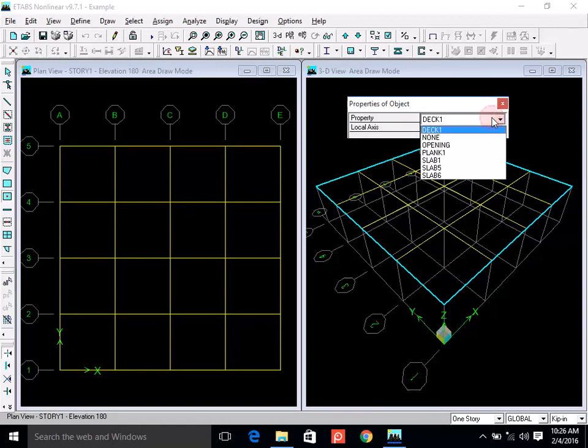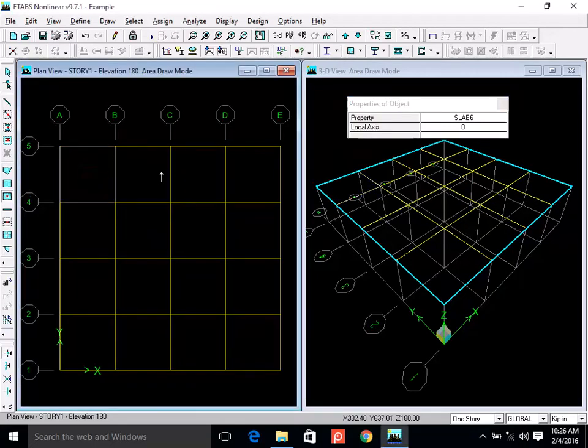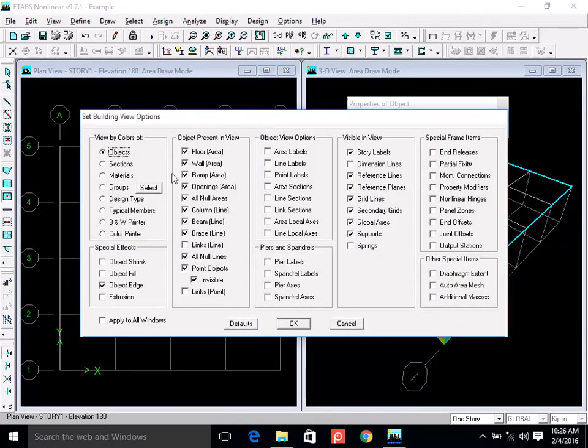Now slabs are right here. We defined 5 inch and 6 inches. So I pick 6 inch, sorry. I click it like this, or I make a window and all my slabs will be in place, right? And I will go to this option and fill these objects. The slabs are now visible, so I can fill this.